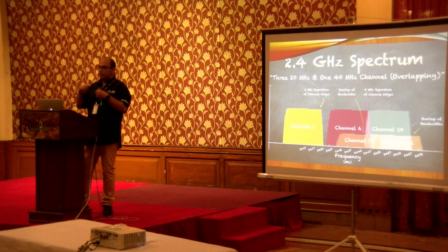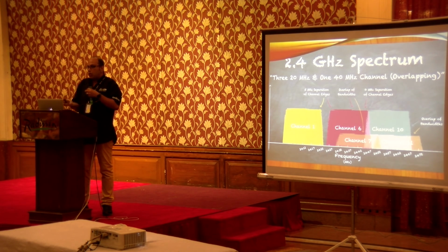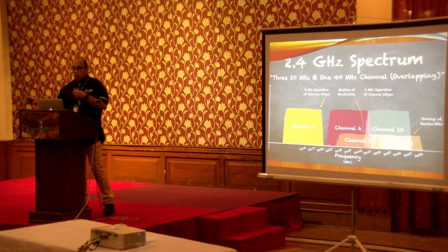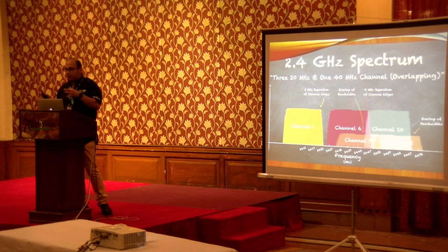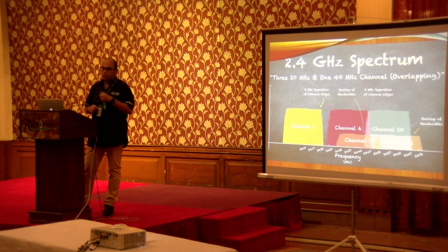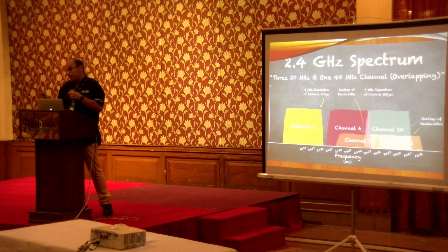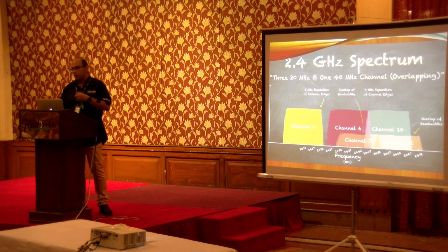What is noise? What is interference? We need to figure out the difference between noise and interference. Noise is actually unwanted power. It's unwanted power. It's a power. That power can come out of the competitor device, your neighbor device, or that power could be by something else. But interference means using or sharing the same channel for 2 networks. This is interference. If you do not follow the channel separation, you may have interference. Depends on environment actually. If you're working in free environment, if there's no any other competitors, so